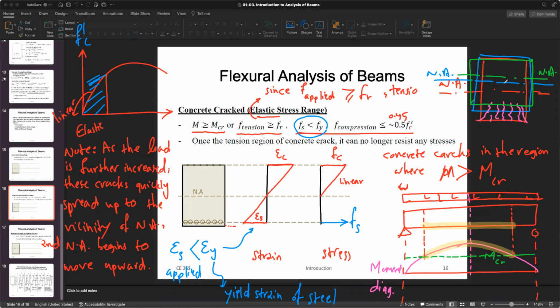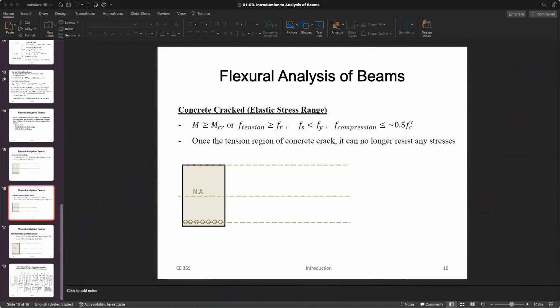All right. So this tendency would keep going until you're totally crushing and reaching this top region. So the neutral axis would be shifted up. That is what we're talking about. Because the cracks are going higher and higher, causing your healthy cross section to be smaller, shrunk and shrunk. Okay, that is a topic. That was the note that I gave you at the end. So let's continue.